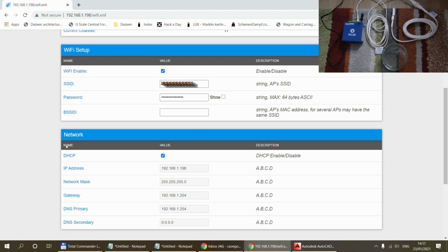And also here in the Wi-Fi setting, we have options to specify a fixed IP address. At the moment, I just left it on dynamic, which is, for this review video, fine. But normally you will untick this and you will specify a dedicated IP address for this device. So it already gives you the options, the gateway and the network mask based on your network settings. So you just have to uncheck this and then specify the IP address. And then from that point, this device would always receive this IP address from the router.